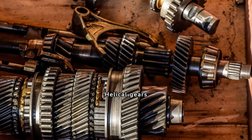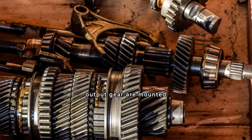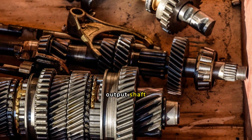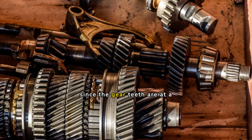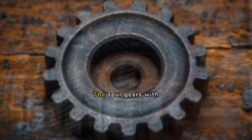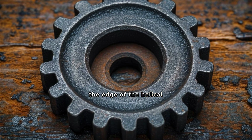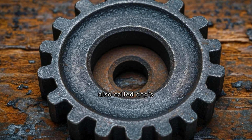Helical gears, namely input gear, counter gear, and output gear, are mounted on the input shaft, counter shaft, and the output shaft, respectively. These gears are preferred since the gear teeth are at a certain angle called the helical cut. The spur gears with straight cut teeth are used on the edge of the helical gears and rotate along with it. It is also called dog's teeth.